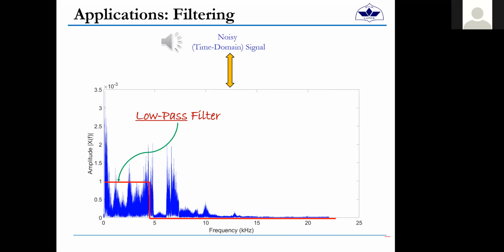A low pass filter is something that allows the frequencies which are lower than this red line to pass, and the frequencies above it are blocked. Excellent. If I may take the liberty of quoting Adil Haider here, he says it only allows lower frequencies to pass, and that's why it's called a low pass filter, because it blocks out the high frequency components. And conversely, what would a high pass filter be? A high pass filter allows the high frequencies to pass and the low frequencies to be cut out. That's one of the things I do in the tutorial task, as you will see.